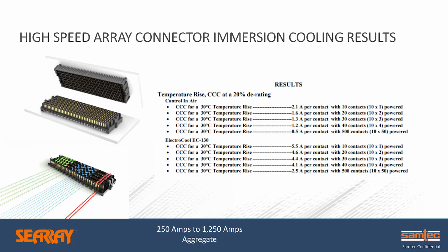If we look at other products and how immersion cooling affects power integrity, that's where you see some major benefits. The series now on the screen is Samtec's C-Ray. If you look at the current carrying capacity from our test reports on the website, if we fully power every single pin in this connector, we average about 0.5 amps per contact over the 500 contacts in this system.